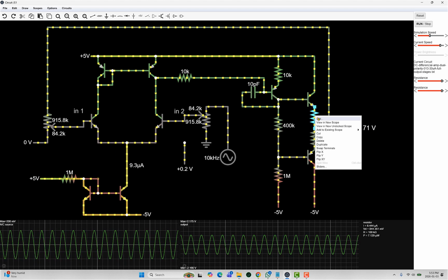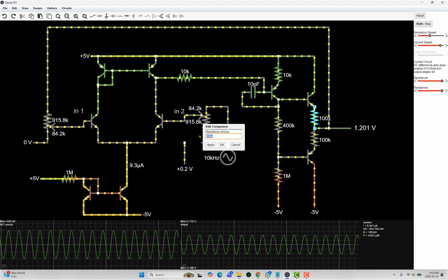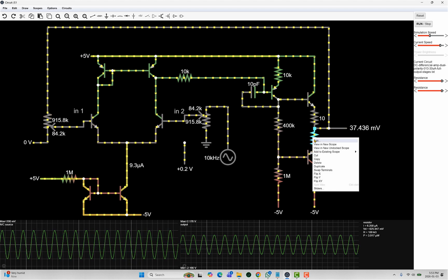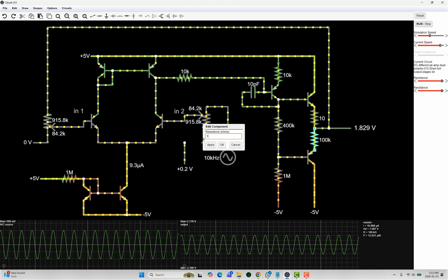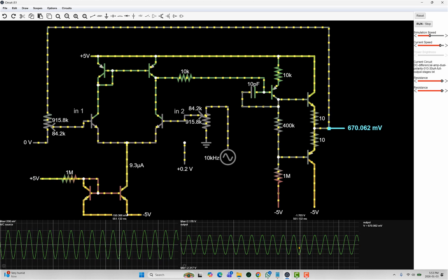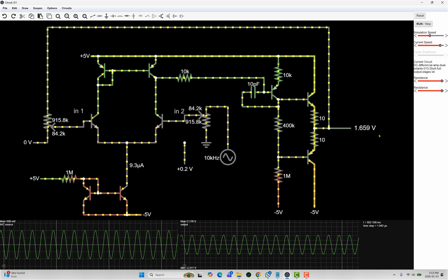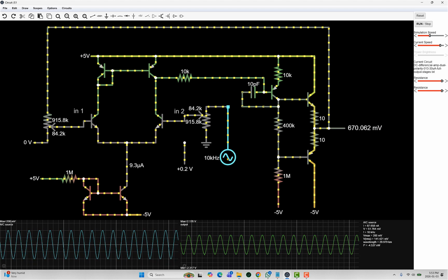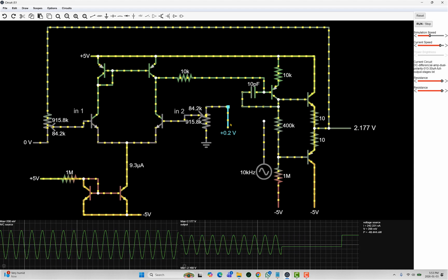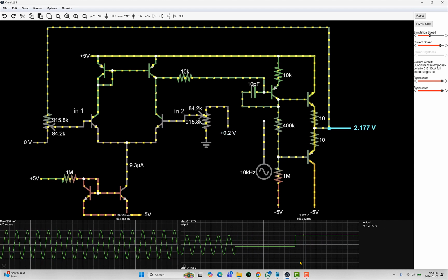Okay, so let's show you this. Let's go down here. They're at 100K. Let's put them at 10 ohms just to see what happens. Well, that's pretty low, right? 10 ohms. Does it still work okay? So now you could drive, yeah, it still looks like we got a clean output. So we could drive some kind of load. Now, let's see here. Yeah, there's my DC.